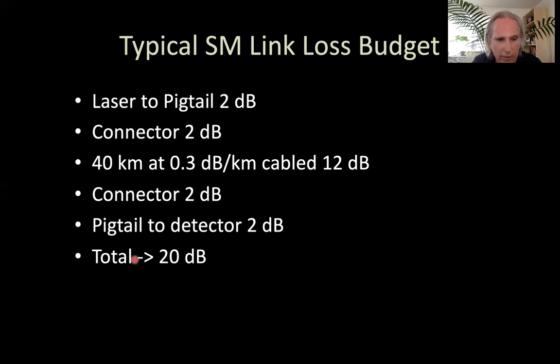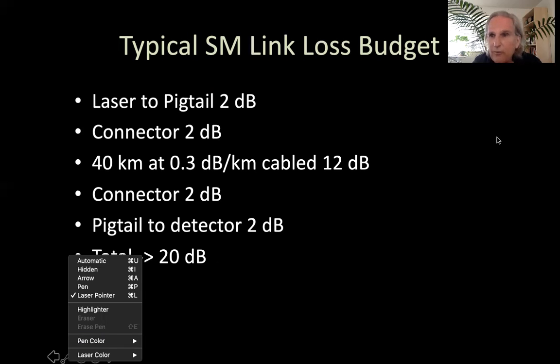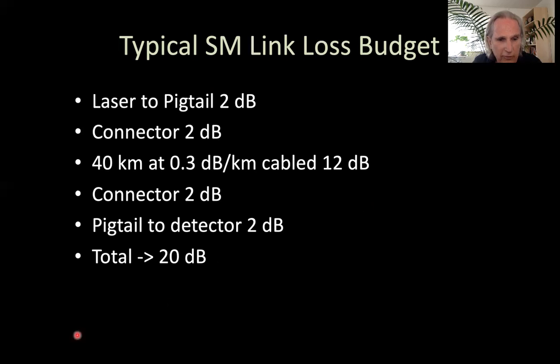The point of all of this is that fiber optic links, yes, they have grown in capacity, and they're tremendously successful, and they're all over the world, and we have all kinds of undersea cables, but a link is limited to around 40 kilometers. You have to start putting amplifiers after that. You have to have power for those amplifiers. That's as far as you can go.